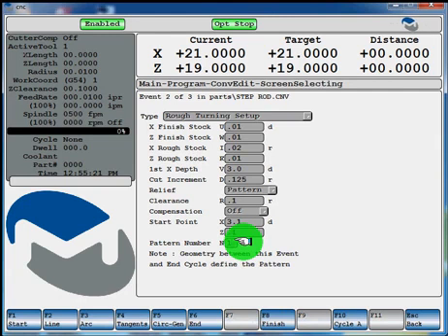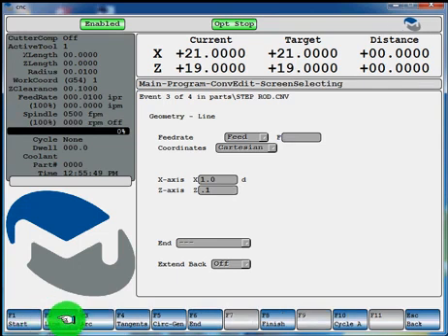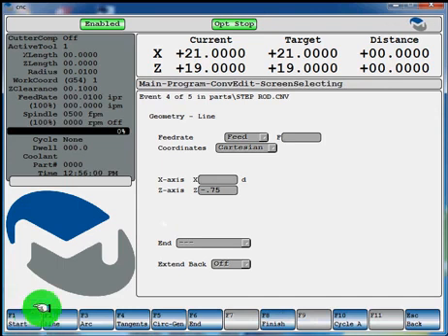And now we're going to define our lines of geometry that we want the cutter to move upon. So the first thing we'll do is put F2 line, and we already filled out our feed rate, so we don't have to do anything there. We'll just give it our dimensions of the part. So we'll make a step rod, and we'll say it's a 1-inch diameter, and 100 thou off. F1 Store. Now another line, F2. And at the 1-inch diameter, we're going to turn it back to 3/4 of an inch. F1 Store.